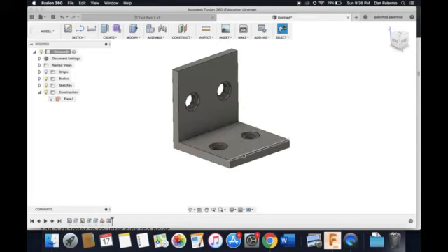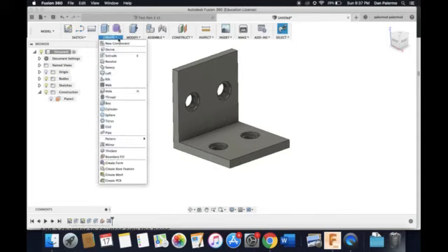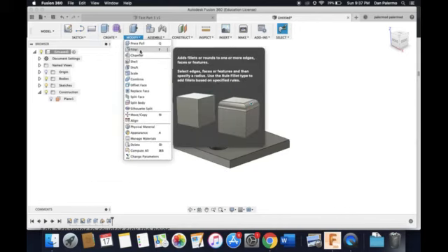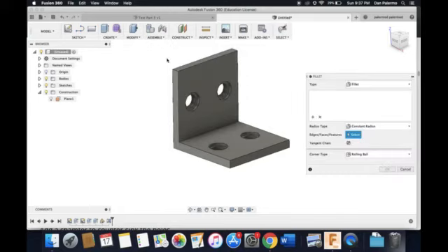Okay. All right, so almost done. All we need to do now is round my edges here, here, and here, so those 4 there, and then put my fillet in. Let's start with these edges. Watch how easy it is. We want to create fillets here, so rounded edges, and that is in the Modify menu under Fillet. Okay. So we can play around with different values for the fillet, but first let's select this corner,